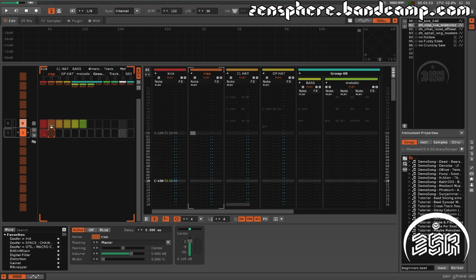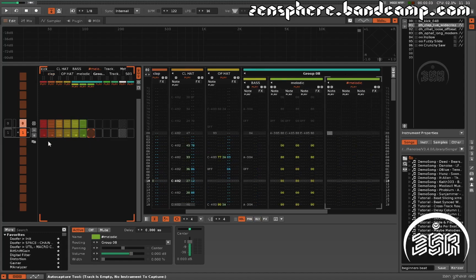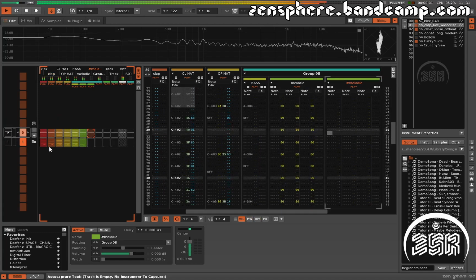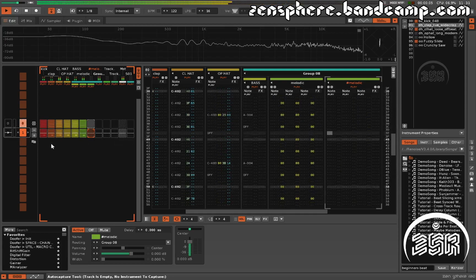You notice when you come towards the bottom edge of this pattern, you get this icon. You can then click and drag downward, which will also clone the pattern. You can do that with multiple patterns at a time, so we can select those and clone those down. And now we have, very exciting, a duplication of that original pattern.